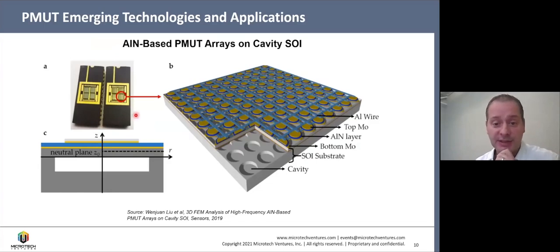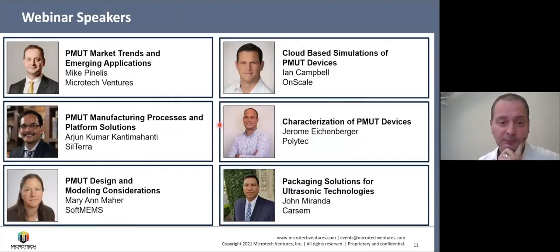This is another example, paper from 2019. Also very creative, very interesting design with aluminum nitride-based PMUT arrays on cavity SOI. So you can see the cavity SOI substrate here, and you've got the PMUT arrays on top.